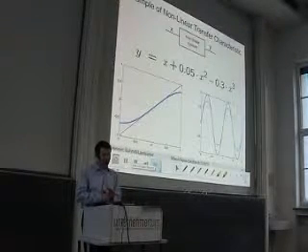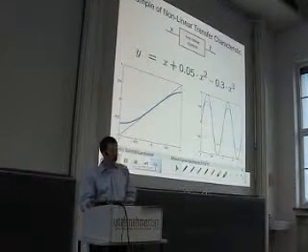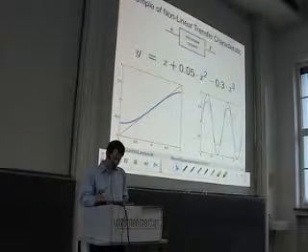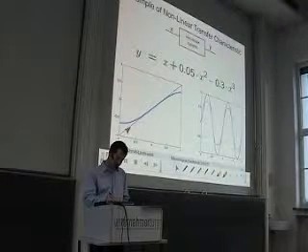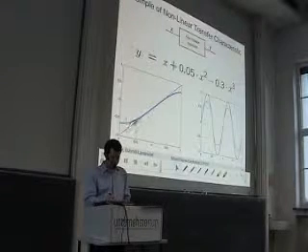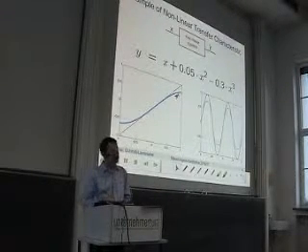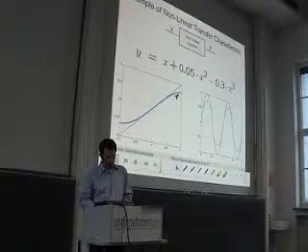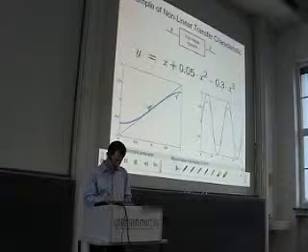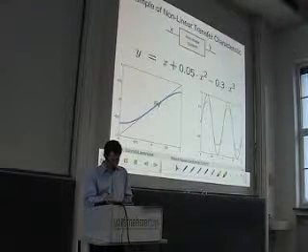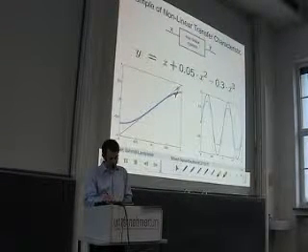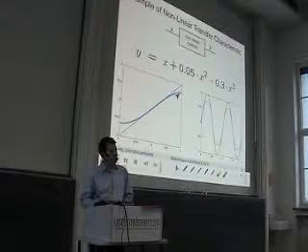This was the last slide that I gave you as a motivation last week, and we saw, for instance, if we have not a linear transfer characteristic as the red line, but something that shows kind of saturation, like the blue line, then if we input a sine with a relatively large amplitude, we see that small values are not or only a little bit distorted, but large values see a deviation from the ideal red case compared to the blue one.